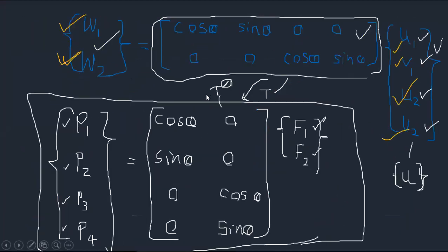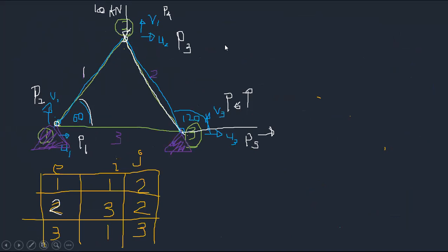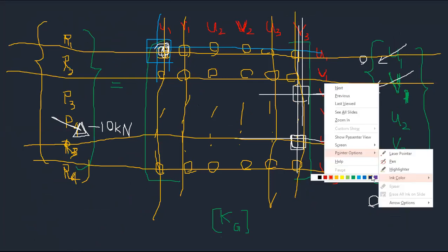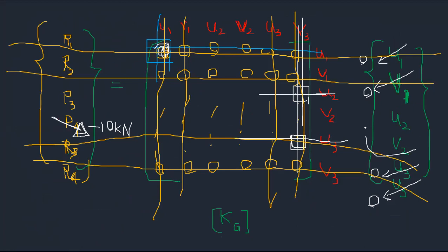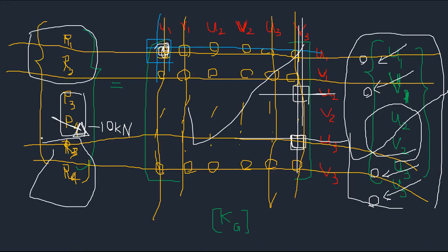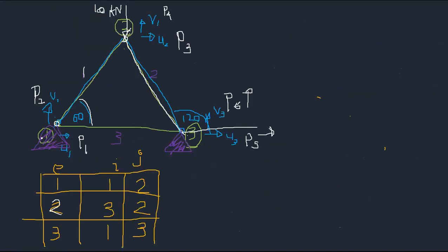So we defined a global stiffness matrix, right? And we assembled it, and what we did was we found the unknown displacements first, right? Using the known forces, right? When we plug back to this, and we know this whole matrix, and we now know the whole displacement matrix, and we found the unknown forces, then now it's clear R1, R2, and R3, R4 are there, right?